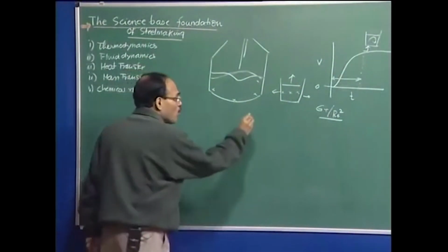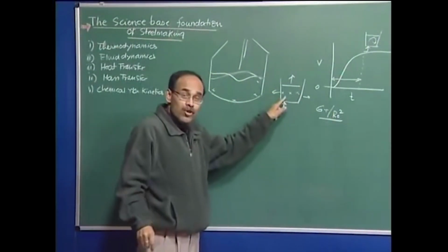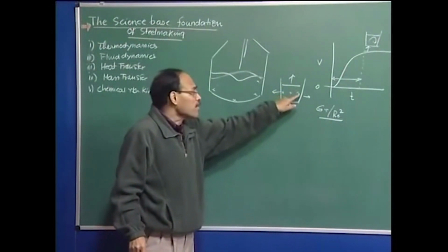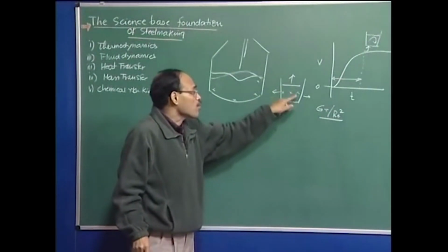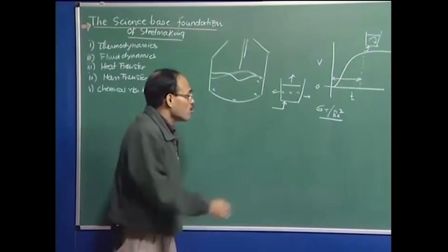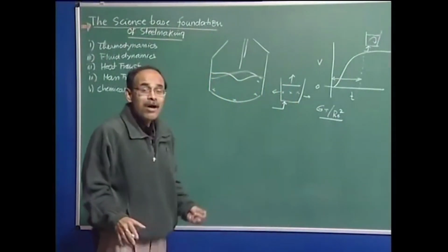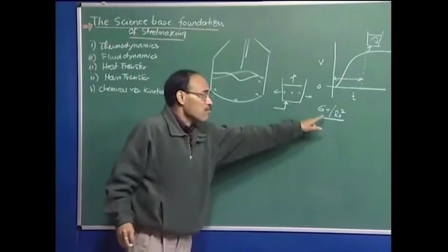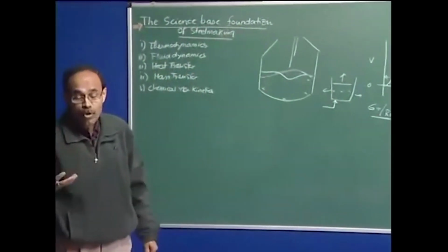On the other hand, when I have gas injection into the ladle, I will have both forced convection and free convection, because free convection will be there because of the temperature differential, thermal stratification in the system, and forced convection flow will be there because of the introduction of the gas itself. Now, whether free convection effects are important or not will be dictated by this particular number. Now, coming back to the issue of non-isothermality.